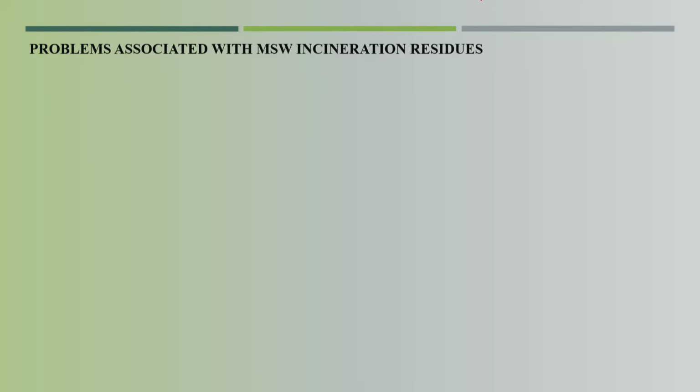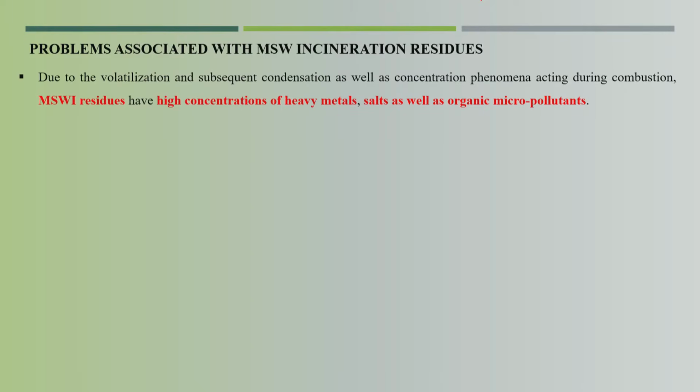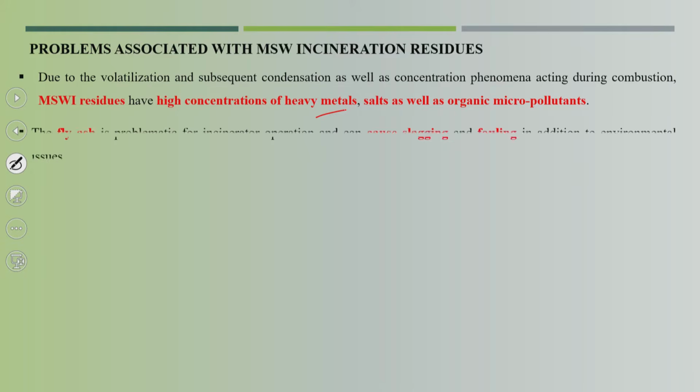Okay. Now, problems associated with the MSW incineration residue. Due to volatilization and subsequent condensation, as well as concentration phenomena acting during combustion, these MSW incineration residues have a high concentration of heavy metals, salts, as well as organic micropollutants. So, the major concentration of heavy metals is problematic.